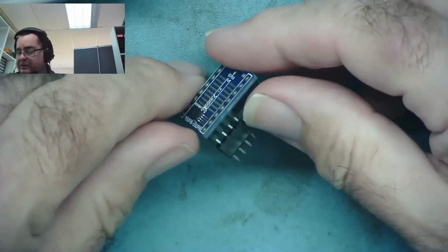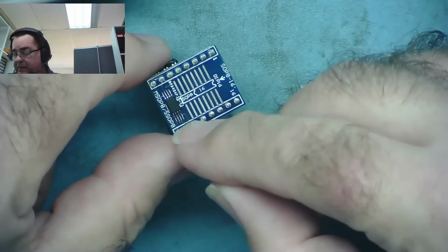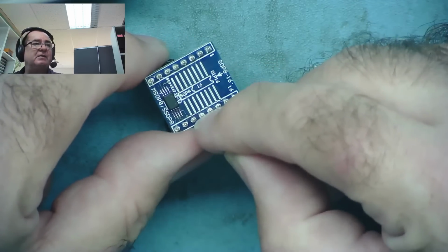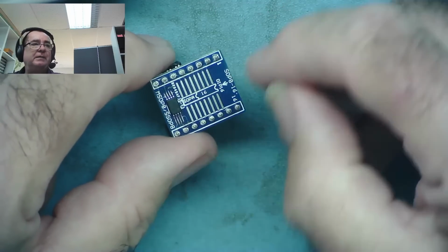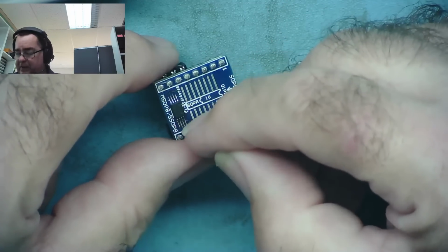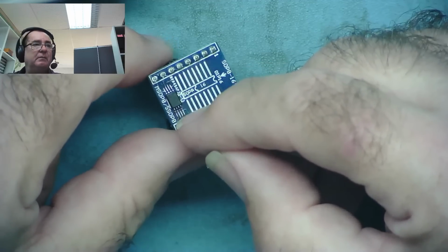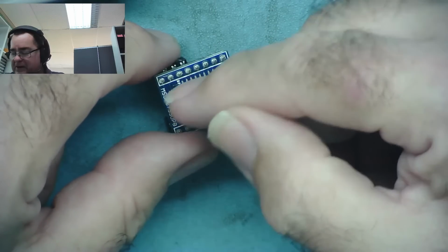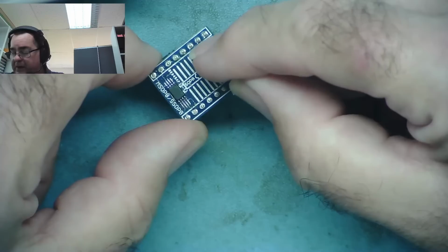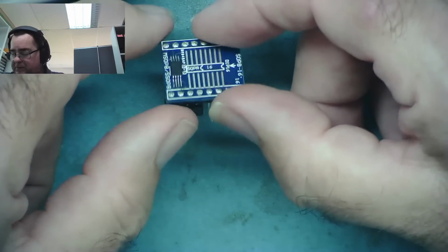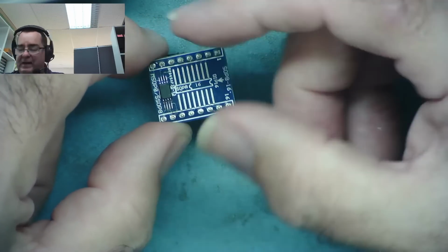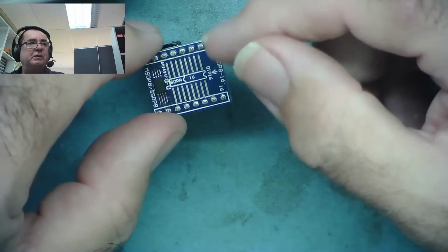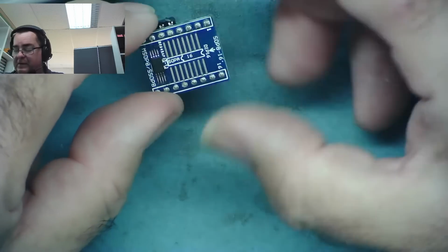And I noticed on this adapter for the EPROM that this EPROM is wired to pins 5, 6, 7, 8, 9, 10, 11, 12. It's not wired from pin 1. And I'm thinking, well, I've got another adapter for the TSOP, which I always think sounds like the sound of Philadelphia, if you remember the 70s, but it's an IC package, TSOP. And it was wired from pins 1, 2, 3, 4. And I thought, oh, strange, I haven't got the right adapter for that package. I've got the adapter for the other package, but I'm assuming when you choose the IC, it knows it's on pins 5, 6, 7, 8, and so on.